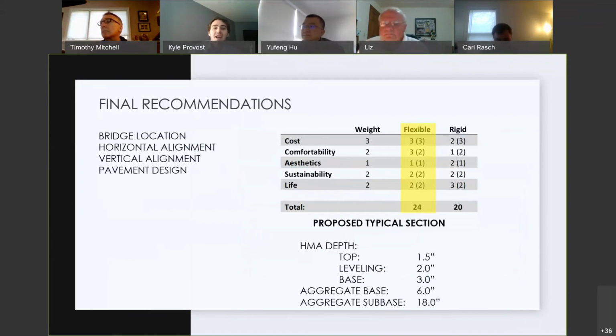But then after we went back and checked with MDOT's preferred thicknesses for application, and using our mixture types, we came up with that 6.5 inches that is necessary in the Superior region. Did you check that the 1.5 inches is the adequate thickness for the 5E3? Yes. That's the lowest. All right. Okay, thanks.